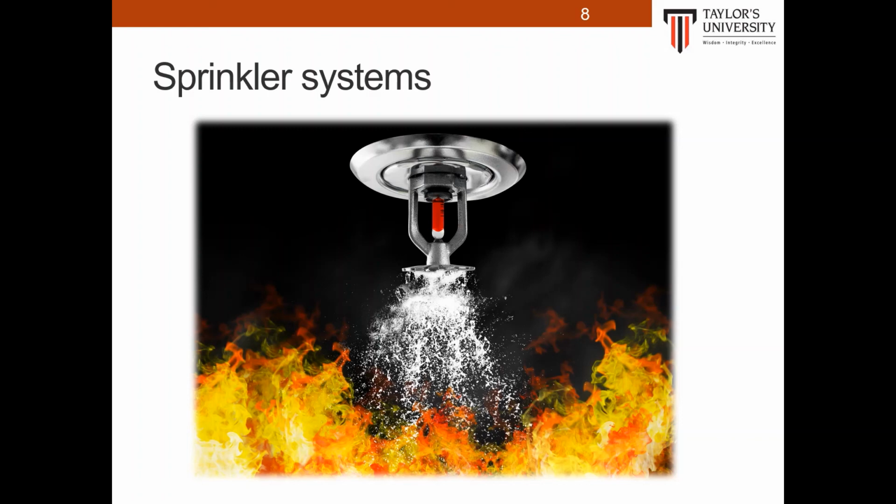This approach is called a deluge system, and the system is used for plant process areas and larger pilot plants. Sprinkler systems can cause considerable water damage when activated, depending on the content of the building and the process structures. Statistically, the amount of water damage is never as great as the damage caused by fire in the area, and therefore sprinklers are still an important system to reduce fire damage.